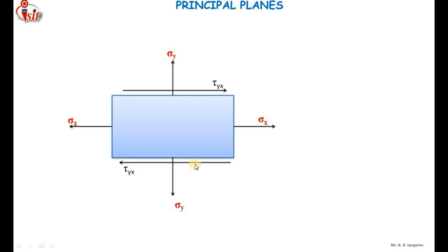Okay, so here you can see that these two stresses are creating a clockwise couple. They are trying to rotate the element in a clockwise direction. So I'm going to apply two more stresses, these are also shear stresses. Here tau xy is the stress which is acting in the downward direction, towards the negative y direction. So x is the area over which it is acting and y is the direction. Similarly, tau xy, here x is the area to which the stress is tangent, and y is the direction, the stress is acting towards the positive y direction.